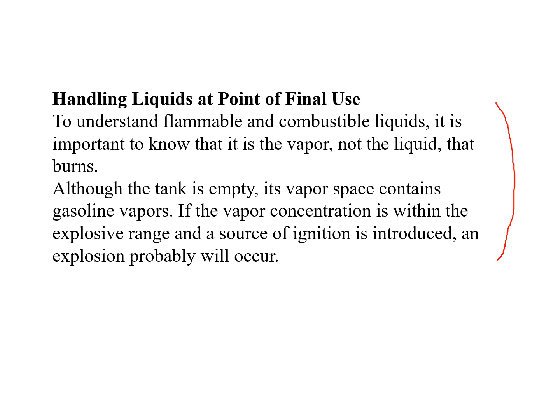For example, if somebody has used flammable or combustible liquids, we need to understand it is the vapors, not the liquids, that burn. Although the safety can is empty once we have used all the liquid, there are still vapors inside the cans, and the concentration of that vapor may be between the flammable limits.